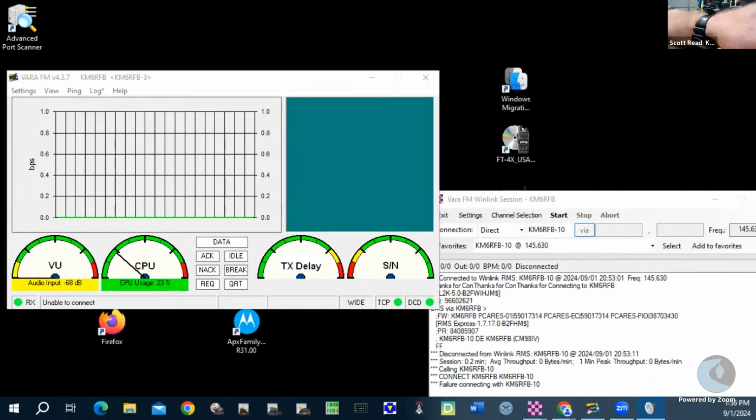No worries. All right, Scott, check that your cable is plugged securely into your radio. Yeah, that's the wiggle problem. The cable there, you had audio for a moment. Yeah, that's a common problem with the Kenwood connectors, particularly in the Baofengs. They just don't sit well.